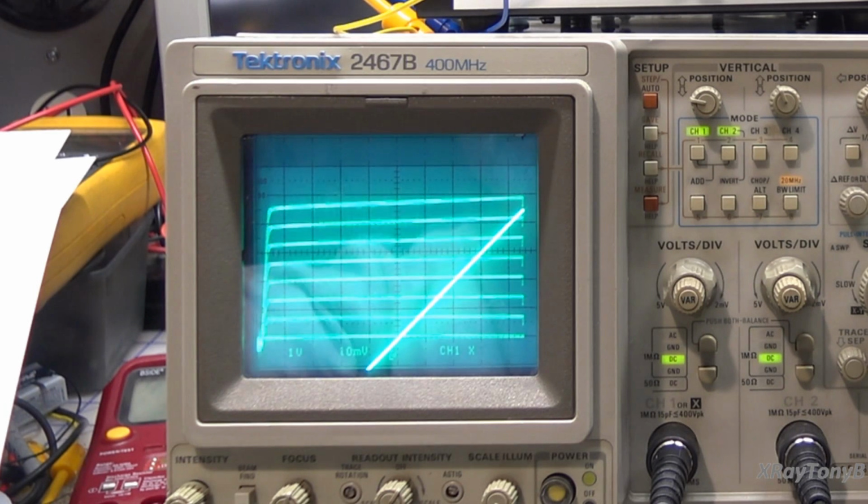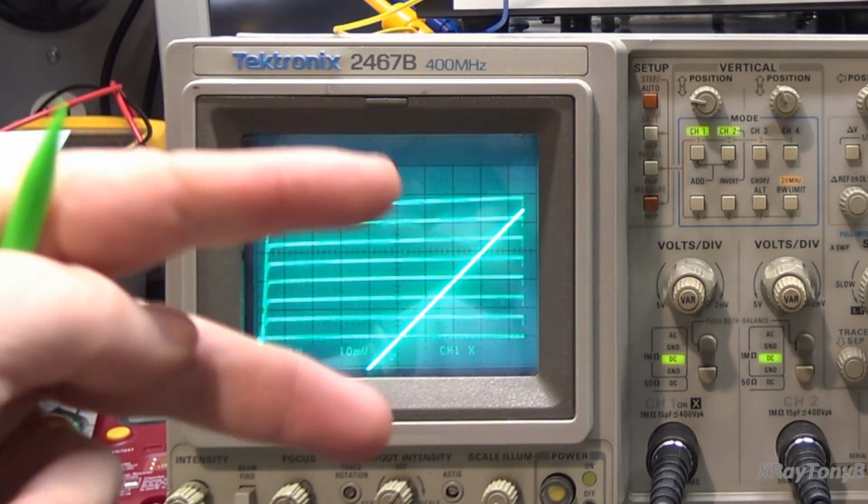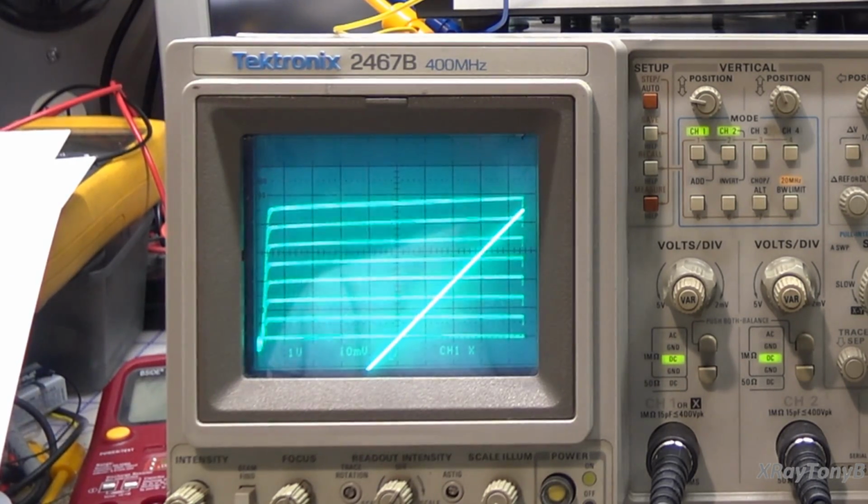You can actually use that early voltage to determine an effective resistance, that would act like the amount of resistance that you have in parallel with your emitter resistor, if that makes sense. So early effect does have some effect on the circuit depending on how it's biased and how it's working.